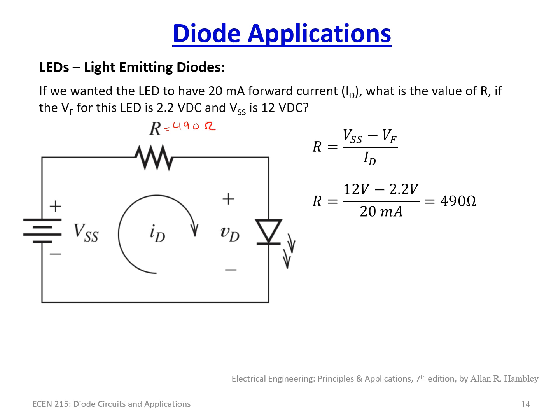This is a very common thing that you do when you're designing controlled lighting in different products. And you would actually go and compute, what is my control voltage? Sometimes it's 3 volts or 5 volts, and you need to determine, probably in this case, a smaller resistor that would accommodate.